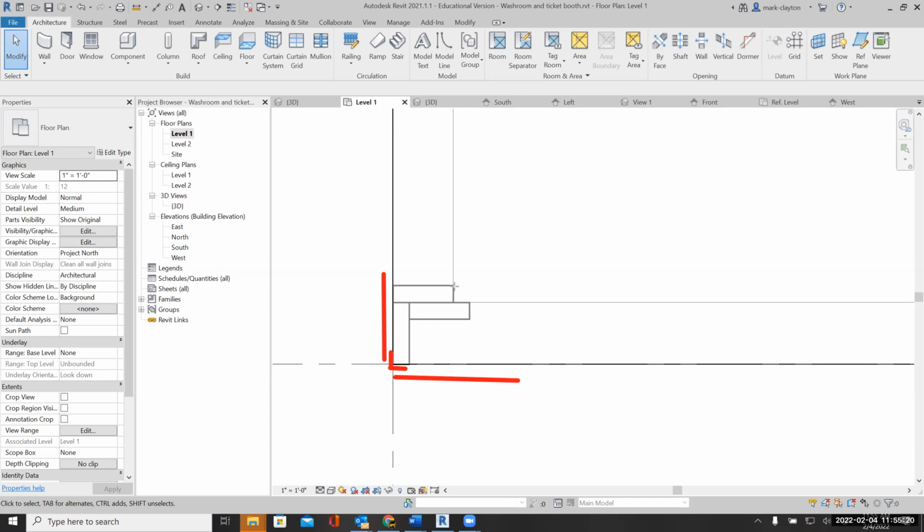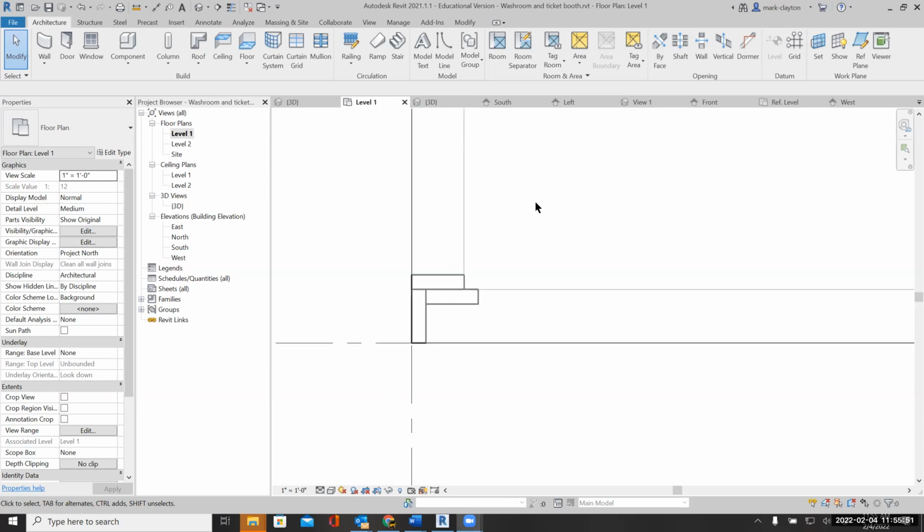And likewise, this is a nailing spot here, and this is a nailing spot here. So when you put gypsum board across here, you can nail it in that way. And when you put gypsum board in here, you can nail it in that way. So the arrangement of the studs allows us to nail the parts of the building together better.